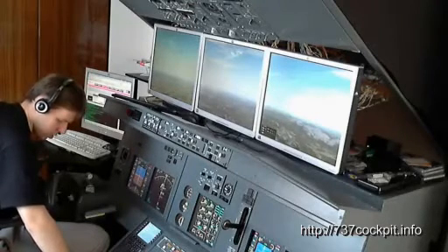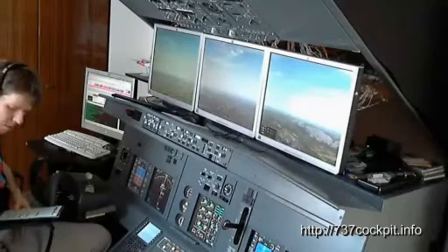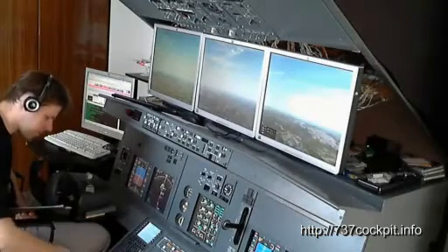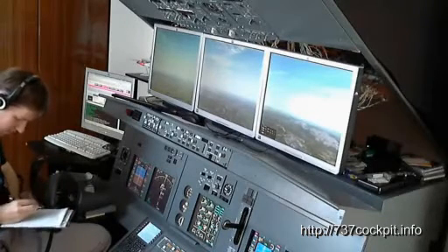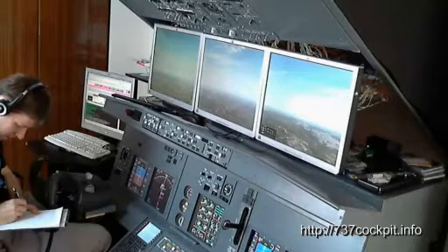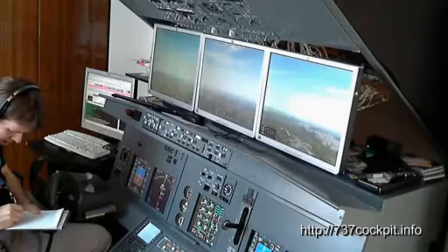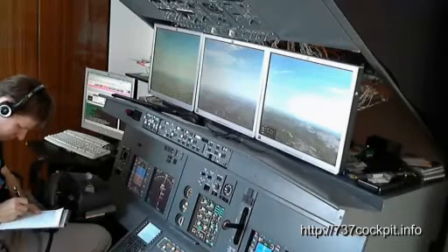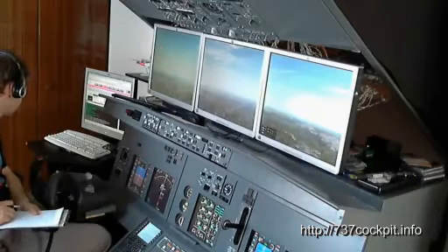So we have now been advised to check the latest ATIS in Vienna and expect ILS runway 11 to the airport. We will switch now to the ATIS frequency and we will write down the actual weather in Vienna. Wind 130 degrees 10 knots. Temperature 6, dew point -2, QNH 1030. On initial contact, advise you have information Charlie. This is Wien information Charlie.